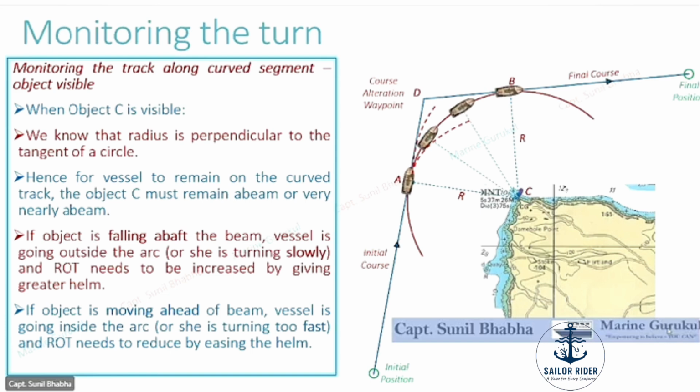Yes. Yeah, there is a certain drift angle during turning. The heading of the ship is not exactly in line with the course being made good. So that much is neglected, beta. We don't go that much deep into it. You can conveniently neglect it without any appreciable loss of accuracy. Okay, sir.